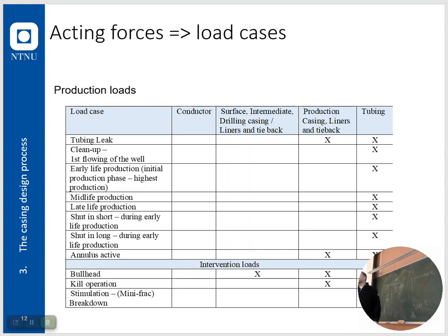A lot of thermal stresses, and not to forget, in this annulus here, the A annulus and the B for that matter, all of them, we say that for 1 degree heating, there is 1 bar increase, as a field rule of thumb.